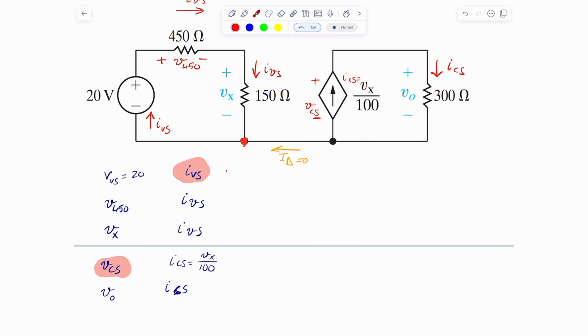Obviously, I can write KCL equations and identify nodes, but I identified this node and I didn't include the I delta, so that doesn't make sense and I don't need it. This node in here, this node in here, and this node here, we evaluated what these mean because they're in circuit with the ISC when I identified the elements. So that leaves me with writing two KVL equations.